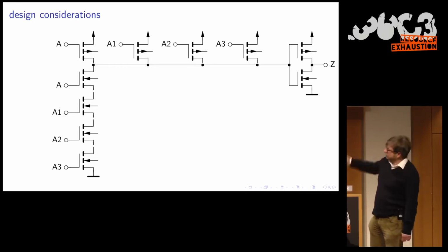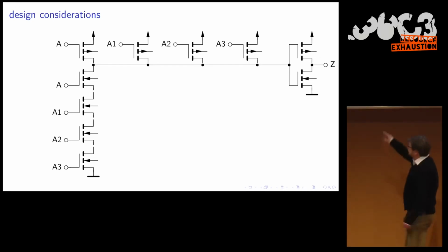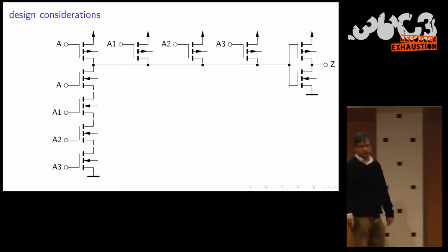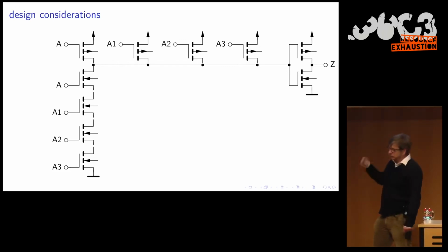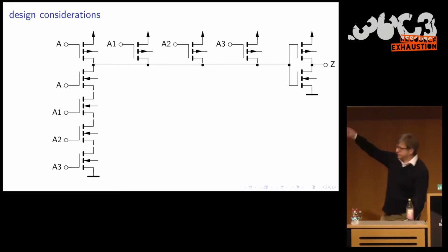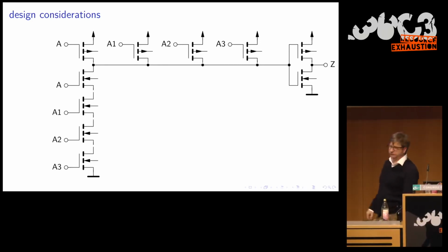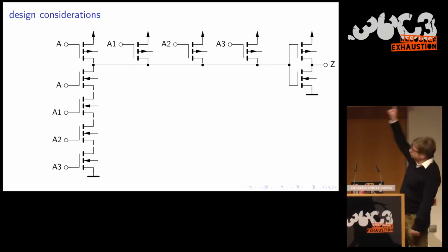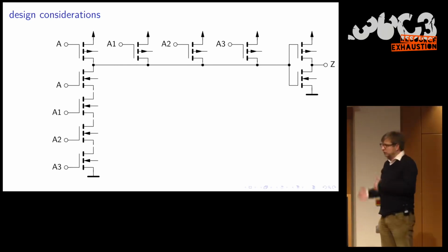When we imagine over each transistor in the long channel, the lower end and the one above, there's a voltage decrease, so there could be a small difference, but when you have this difference 4 times, then this difference adds up, and this can cause the output level to not be big enough.